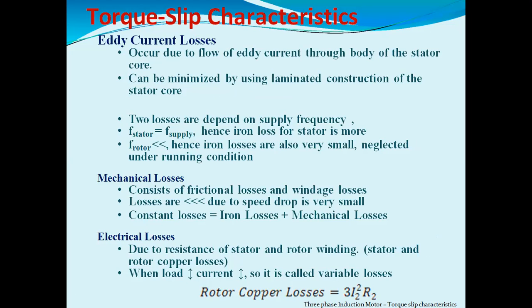And here eddy current loss again we will get, because of the flow of eddy current through the body of the stator. It means that if you are not doing the grounding properly, at that time current will flow, and we call that current eddy current loss. We can minimize that loss by using laminated construction of the stator core.